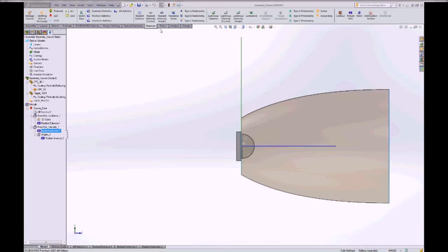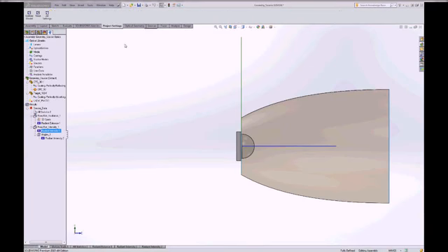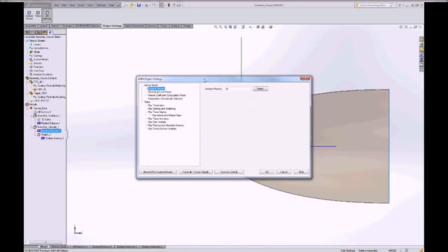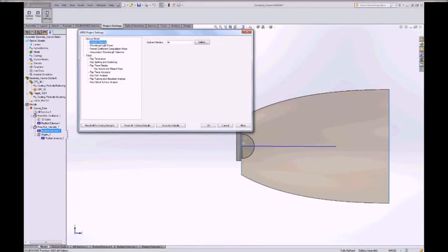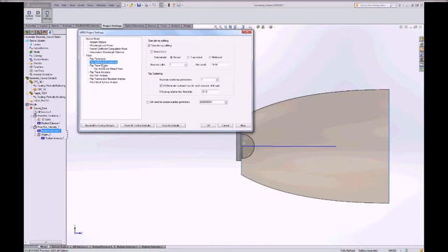And I would like to talk about, before we do the trace, just one other area, and that's what we call the project settings. The project settings allow you to set some parameters. You can define the ambient medium, which is the medium of the world around your system. You can set how you want Fresnel effects to be calculated, reasons for terminating ray traces, splitting and scattering. And in this limited time, I don't want to go into too many details. I could spend an hour just talking about what some of these settings mean.